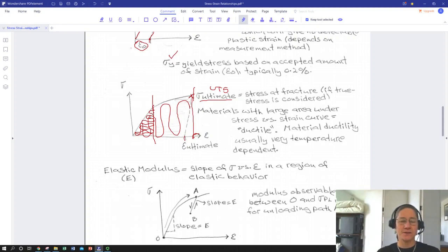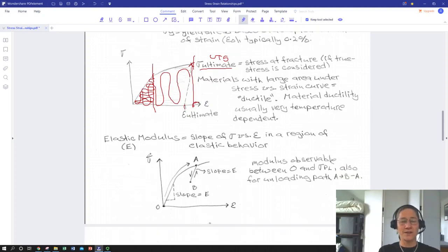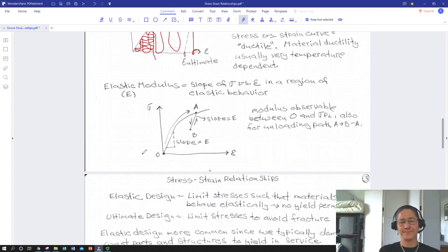In this case, it was just a uniaxial tension kind of deformation, but that's another elastic property, elastic strain energy. And for those of you who are going further in the field of material science or failure, this elastic strain energy is the driver of crack propagation, as it turns out. You'll have some of this strain energy at the tip of a crack, and releasing that is the energetic drive for crack propagation. So it's not always your friend.